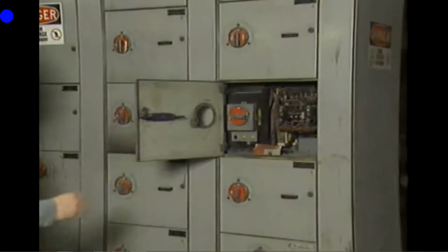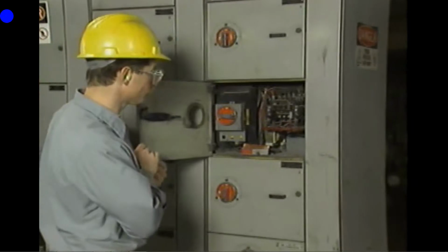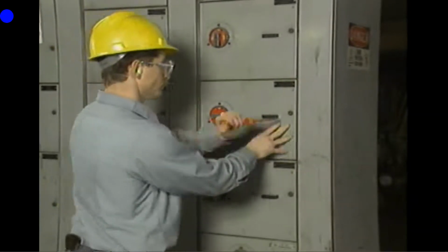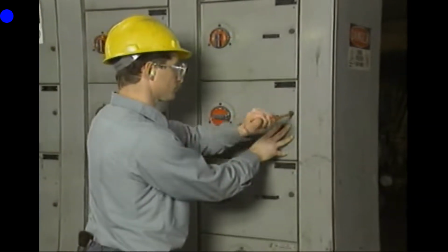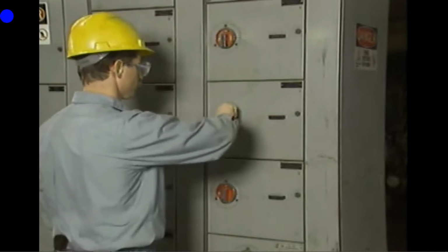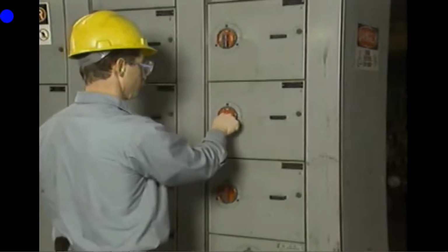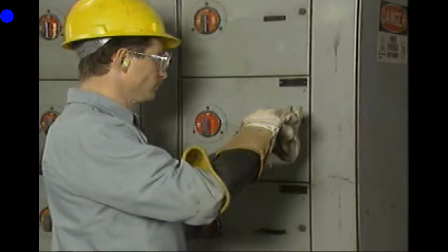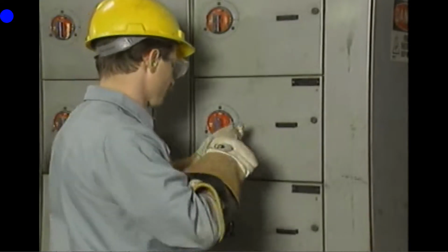In some cases, you may need to test run the controller so that you can observe the malfunction firsthand. But test running a controller can sometimes further complicate the problem. For example, if one of the symptoms was the smell of burnt insulation or smoke, a test run could further damage the insulation or cause a fire in the controller, so the situation should be evaluated before a test run is made. And whenever you do make a test run, make sure that all applicable procedures are followed.